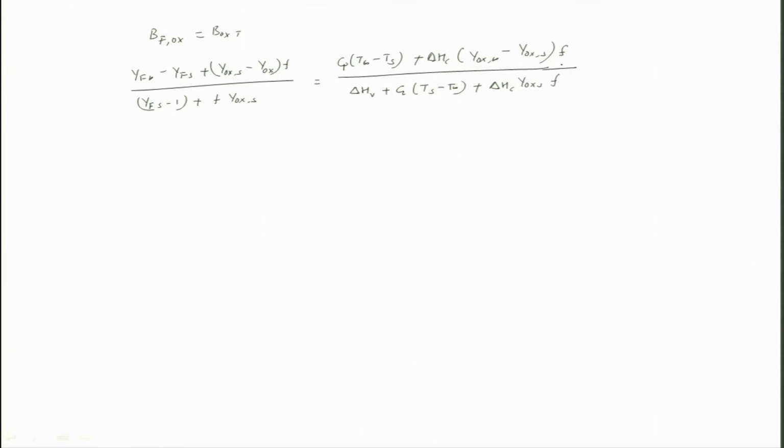So for the combustion case, keep in mind that these transfer numbers are valid for vaporization and combustion. For the combustion case, what is Y_oxygen at the surface of the droplet? It will be 0. If you take a droplet and there is a flame here, then at the surface, oxygen cannot penetrate through the flame.